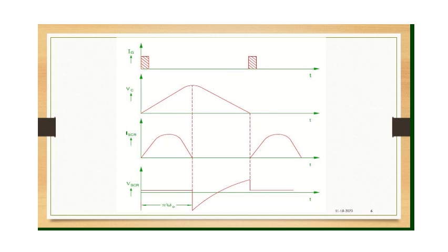That is when the inductor will reverse. When the inductor reverses, it dissipates its energy to the capacitor, charging the capacitor further, and the current in the SCR is now dropping. It drops to 0, and that is when the SCR will turn off.